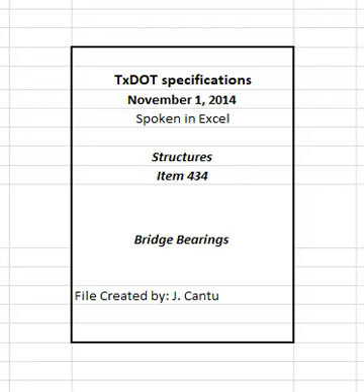2.3.3.3 Miscellaneous components. 2.3.3.3.1 Lateral guides. Provide guide bars integrated with the steel top plate and interface components of stainless steel facing and PTFE for guided HLMR expansion bearings. Submit alternate interface components to stainless steel and PTFE for review and approval. Provide details indicating guide bar, stainless steel, and PTFE attachment and design to sustain the lateral loads specified on the plans while maintaining unimpeded expansion capability.